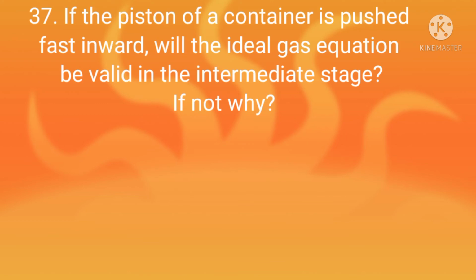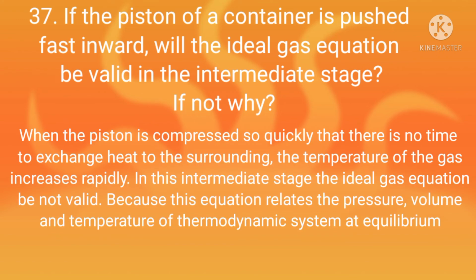Then question number 37. If the piston of a container is pushed fast inward, will the ideal gas equation be valid in the intermediate stage? If not, why? The answer is, when the piston is compressed so quickly that there is no time to exchange heat to the surrounding, the temperature of the gas increases rapidly. In this intermediate stage, the ideal gas equation is not valid because this equation relates the pressure, volume and temperature of the thermodynamic system at equilibrium.